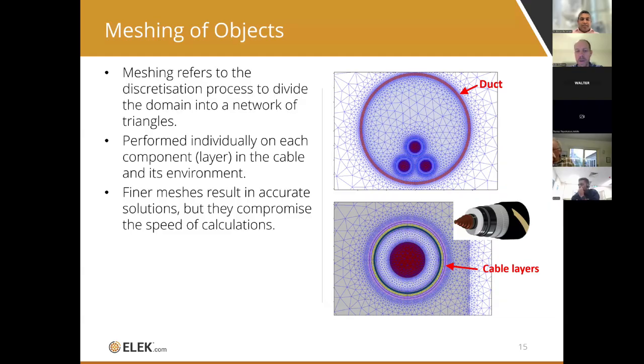But there's also air convection inside this duct, which typically also needs to be modeled, right? This is one of the disadvantages of the IEC method, where they consider some analytical models for air convection, with fixed constants. So that's why you cannot change the material of the duct in the IEC method.